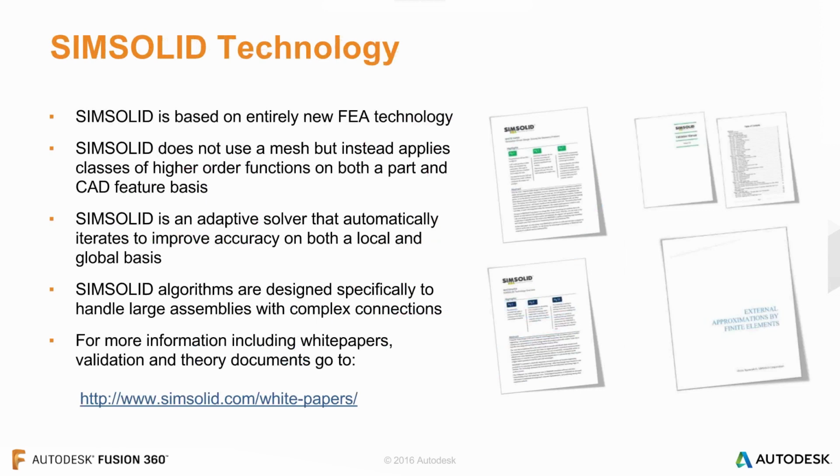So the technology in itself, that's a separate presentation. But what I will say about it is that what we're using is extensions to the method of external approximations. It's an adaptive solver, so it's like kind of adaptive H or adaptive P solvers in the traditional FEA world, where we take an initial set of equations and then we locally enrich it on a pass-by-pass basis, looking at the errors that are in the model and to minimize the errors.